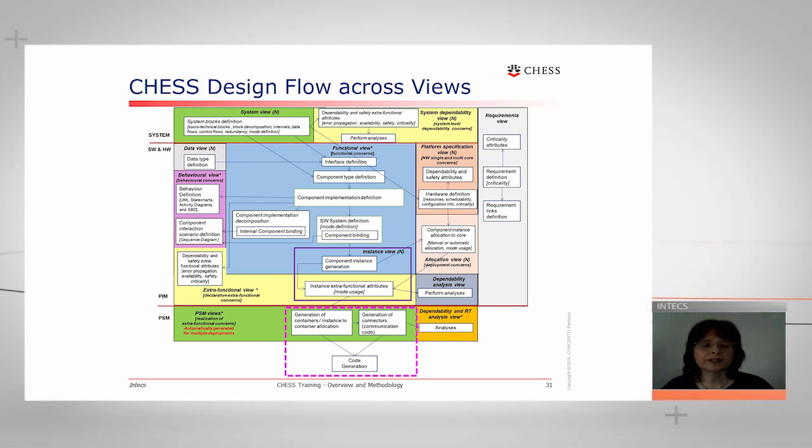At this point, the PSM platform-specific model can be automatically generated, generating the containers and connectors, with automatic code generation, which includes also the code needed to support runtime monitoring. The runtime monitoring allows to perform simple analysis of runtime traces, statistical analysis of the monitored values, computation of the worst-case execution time bounds for tasks running on a multi-core platform, and runtime verification of functional or extra-functional properties of the deployed application.